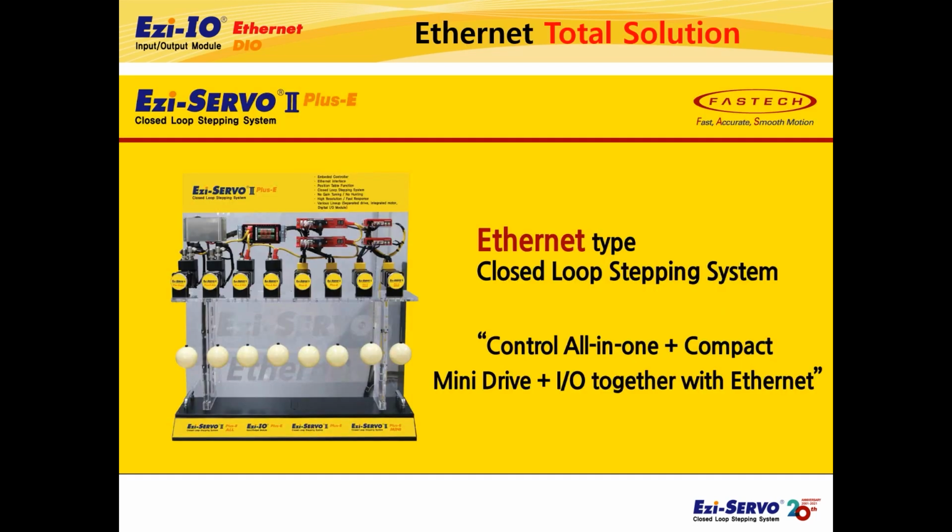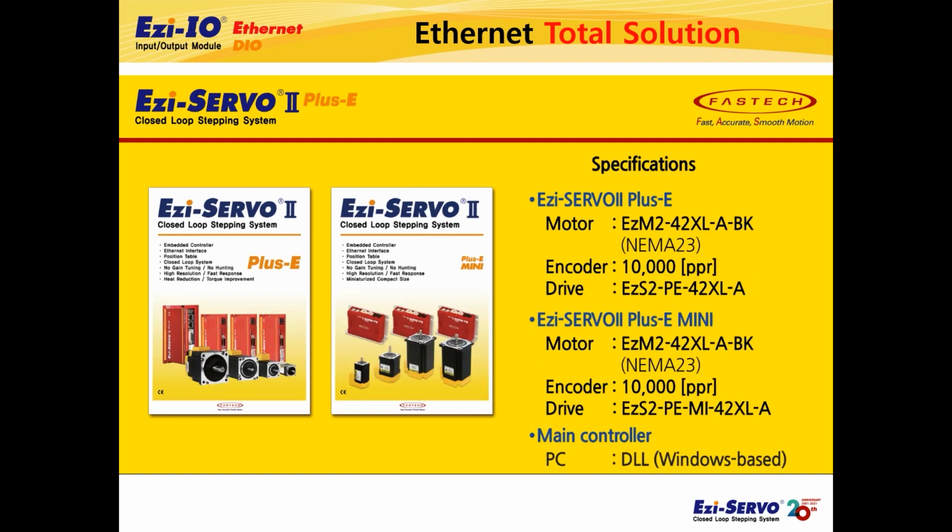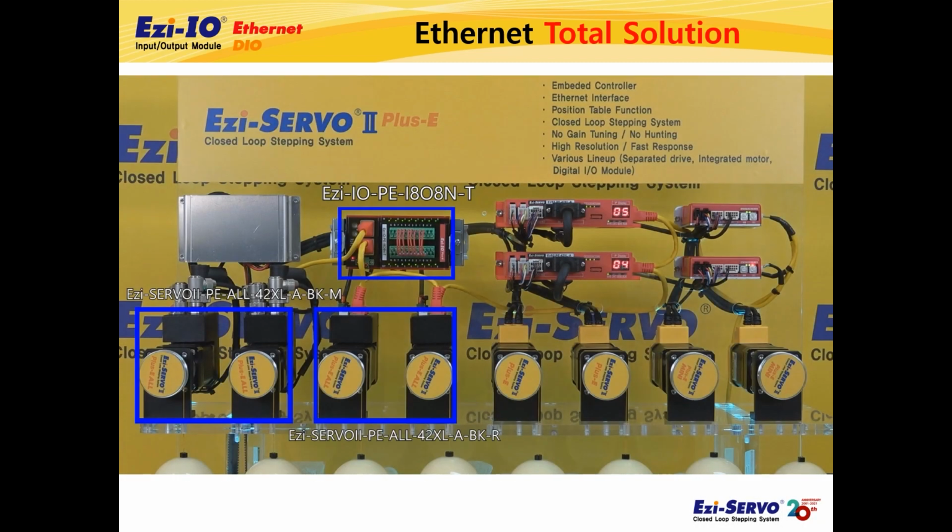The last demonstration is an 8-axis ball demo showing the Ethernet total solution provided by FASTECH. The product names used in this demonstration are as follows. If you look at the left side, there are 4 axes of Ezi-SERVO 2 plus E-all, which is an all-in-one type that combines a motor, a high-resolution encoder, a drive and motion controller, and Ethernet network. And there is a digital I/O module, Ezi-IO Ethernet DIO.